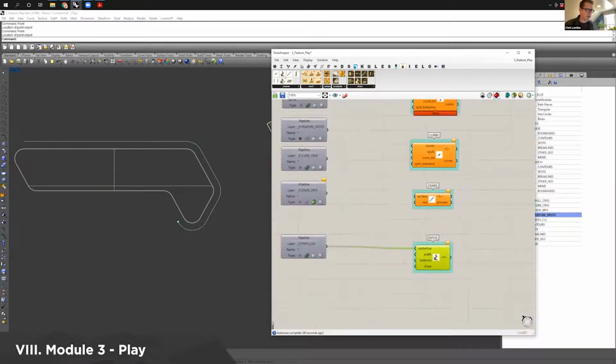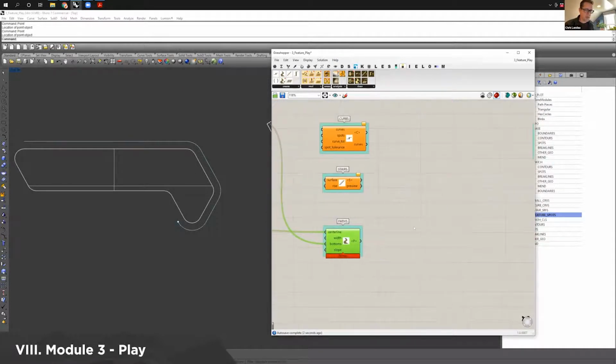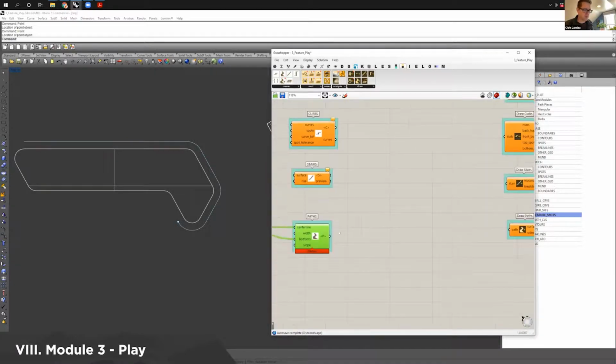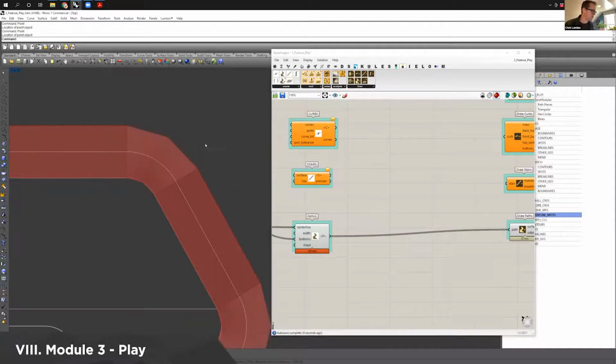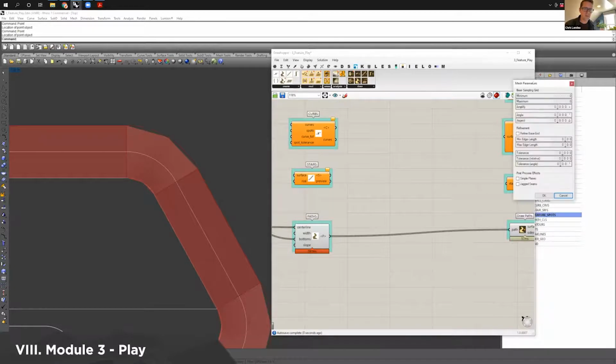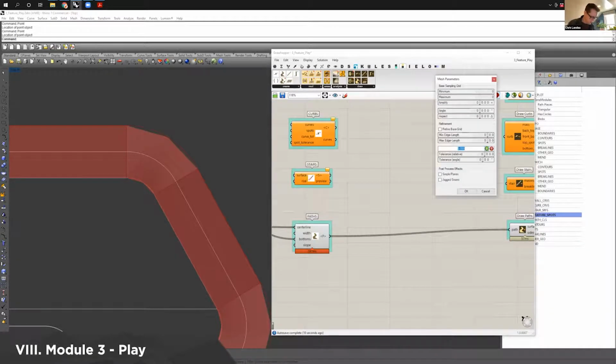And we plug the spots into here. And now we have a path. It's not being drawn yet, so we just plug this over here into path draw. And there we go. We have that. And again, I'm seeing that weird issue with my Grasshopper preview, which I'll change to 0.01, which is about 1/10 of an inch.